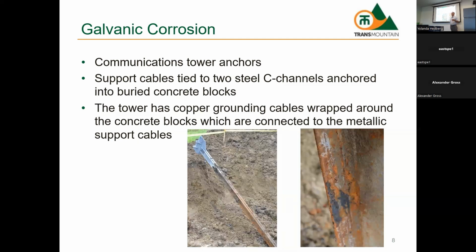I would say, without what was going on, which I'm going to talk about, if that wasn't happening, this wouldn't have corroded. The galvanic in the soil should still have been intact. It was only 10 to 15 years old. It's in the soil, it's galvanized. It should have been fine. Okay, so there's something else going on here.